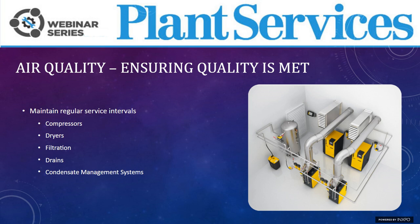Compressors, dryers, and filtration, usually these are the main focus of service. However, don't neglect your drains or your condensate management system. These could be your weakest link in the system. For example, if a drain fails, water can be entrained in your air system, which can then be pushed to the point of use, creating significant scrap or rework rates.